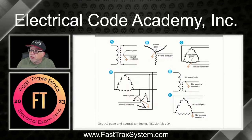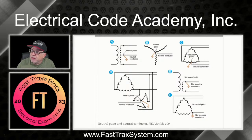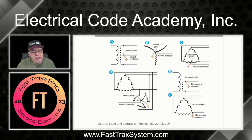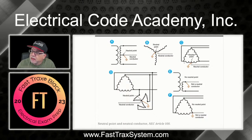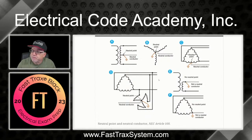Number 3 is an example of a 3-phase delta 4-wire system. And right here is your midpoint. From here to here, it's going to be 240, or could be 480. And then in this winding, if this is a 120/240, from here to here this would be 120. So that is a neutral conductor in this configuration.